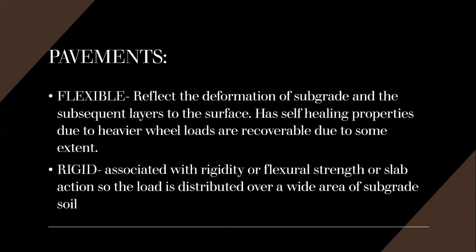In flexible pavement, again, the stability depends upon the aggregate interlock. Then, the rigid has a structural strength provided by the pavement slab itself. Now, in flexible pavement, the pavement design is greatly influenced by the subgrade strength. However, in rigid pavement, the flexural strength of concrete is a major factor for design.